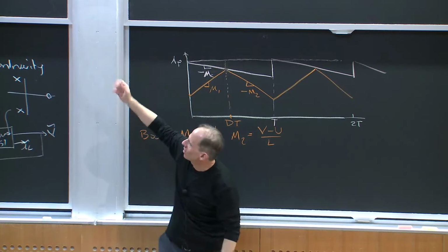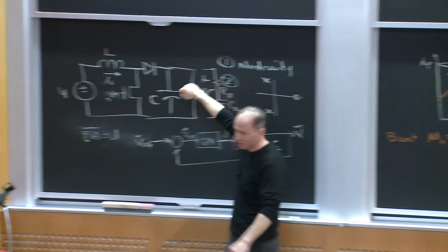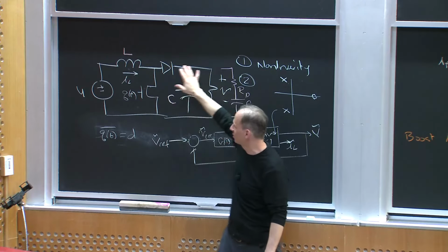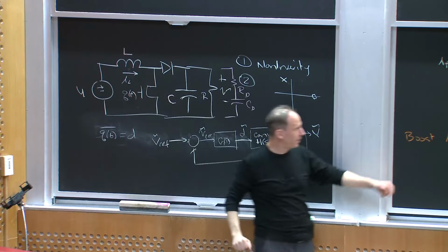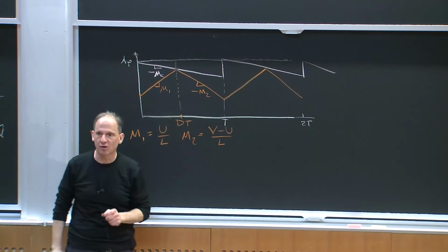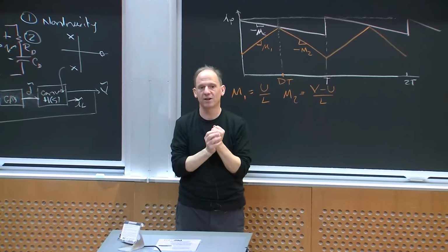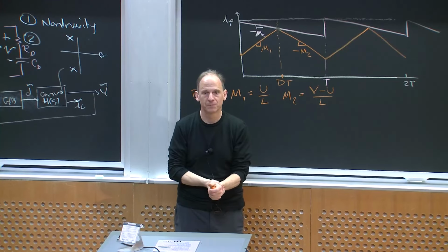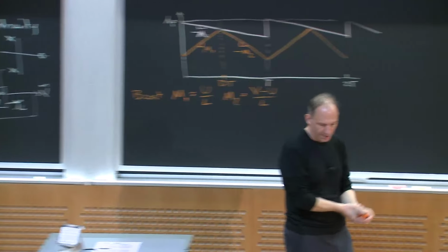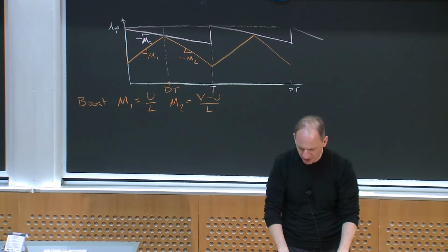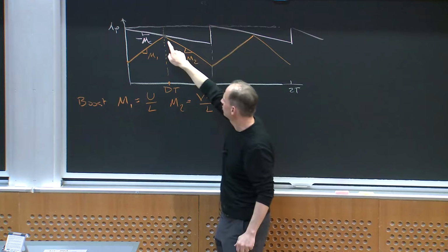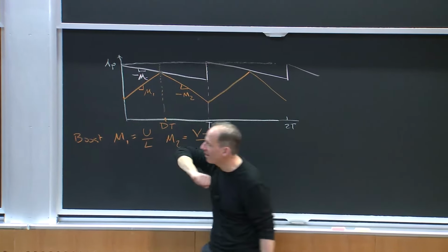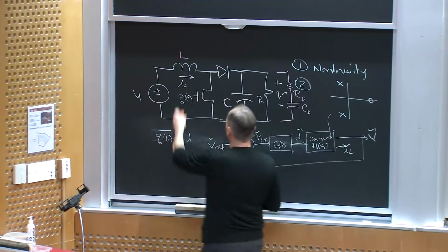Now, in a boost converter, that's not quite true, because if I put a short circuit on this, there's nothing I'm going to do, right? Because the switch won't control the inductor current. But as long as the output voltage is bigger than the input voltage, by having this peak current reference, I can always limit the amount of current the converter's processing, and hence prevent it from overheating, for example. Okay. All right. So essentially, this technique gives me cycle by cycle current control over the inductor current. Now I have to sense the inductor current, right? Because I'm controlling IL here.